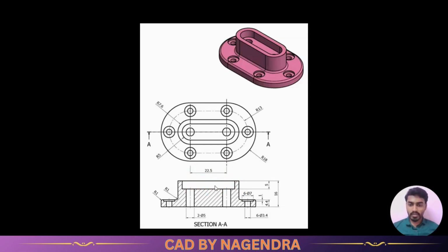Now as we can see, we have a base here with a height of 4.4, but we don't know with which shape we need to add material here. If you see this projection view from top, we have this curvature profile. So this curvature profile we are able to see from top. So we need to create that shape on the top plane only. Why? Because this curve we can't create with the front view.